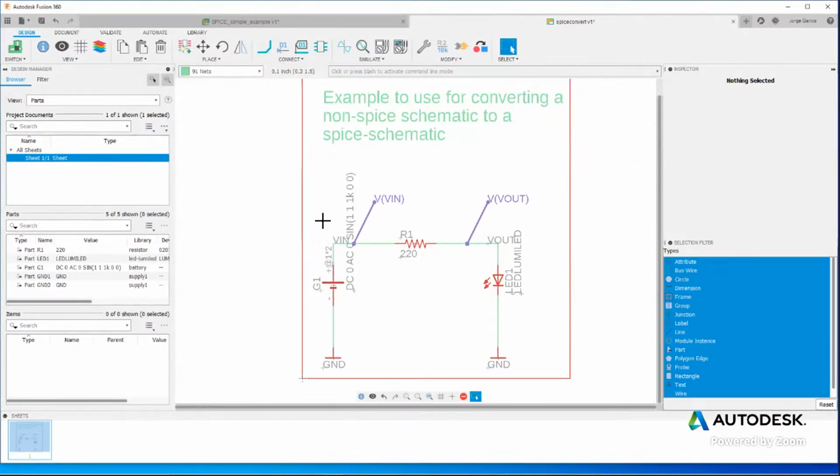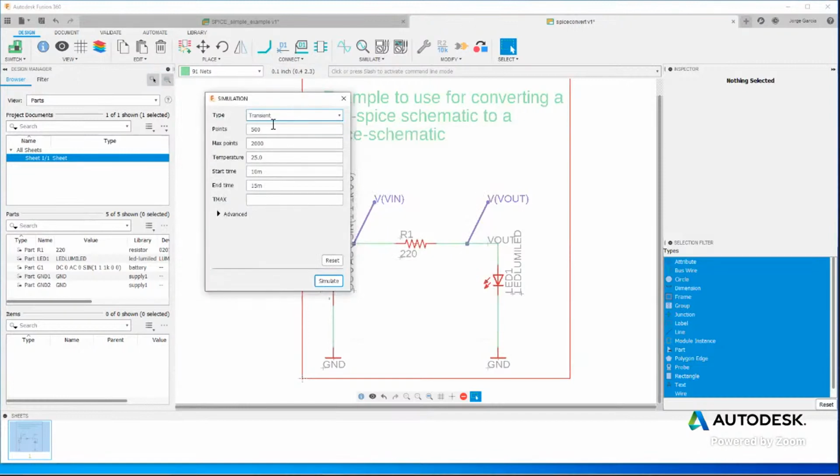That's it. Now we're ready to set up our simulation. So we're going to click here on the simulate button. Now you'll notice there are several options here. Okay. Operating point is the simplest of all the simulations. What it will do is at DC, in other words, there's no transient behavior whatsoever. It will calculate the voltages at all the nodes, and it will also calculate the current through any independent sources. So typically when students run into circuits 1 classes, this is what they're doing. They're calculating the circuit's operating point.